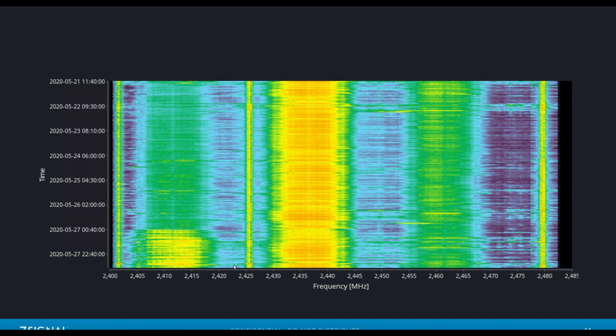The other thing that I notice here that's really interesting is that you can see on channel 6 the transmission is not using the full 20 megahertz width. You see that? Whereas on the one before, it was kind of like from coast to coast. Here, you can see the signature is less than the full 20 megahertz wide spectrum. Now, Jim, I believe this is a good signifier of using lower, slower data rates, is it not?